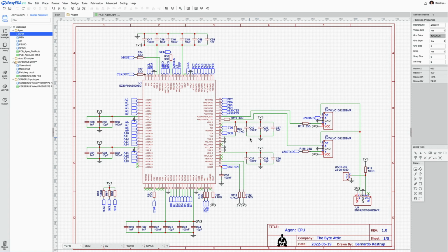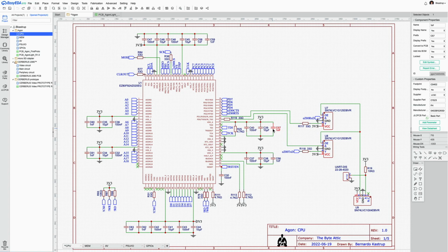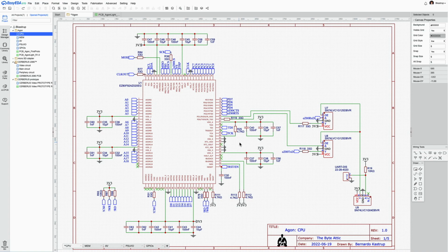The only bad thing that this gives you is not the price. This thing costs fractions of cents, but it makes the layout job a little more difficult because you have to put all 3 capacitors close to the respective VDD pin. Otherwise, they don't do their job. And the more capacitors you have to put close, physically close to a pin, the more complicated your layout gets.